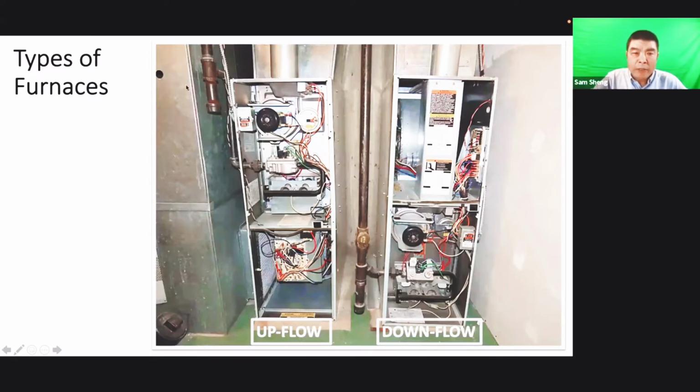So what we should know is the airflow. From the return it goes through the filter. For some furnaces the filter is very hard to take out. I think the home inspector should know that, make notes there, and if they can, change it. The technician should change the filter rack and make it easier to change. Sometimes it's very hard to change, and that's not good, and the customer doesn't want to change the filter because it's very hard to get it. So that causes lots of trouble.